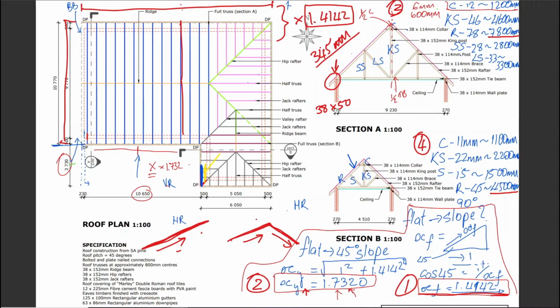The flat dimension is still having to convert itself by 1.4142. Same story here. This flat dimension still has to convert itself to get to that. It is not concerned with what exactly is happening with the roof, but it's only concerned with how it needs to transform itself to get to this slope. Okay? It shouldn't keep you up at night.